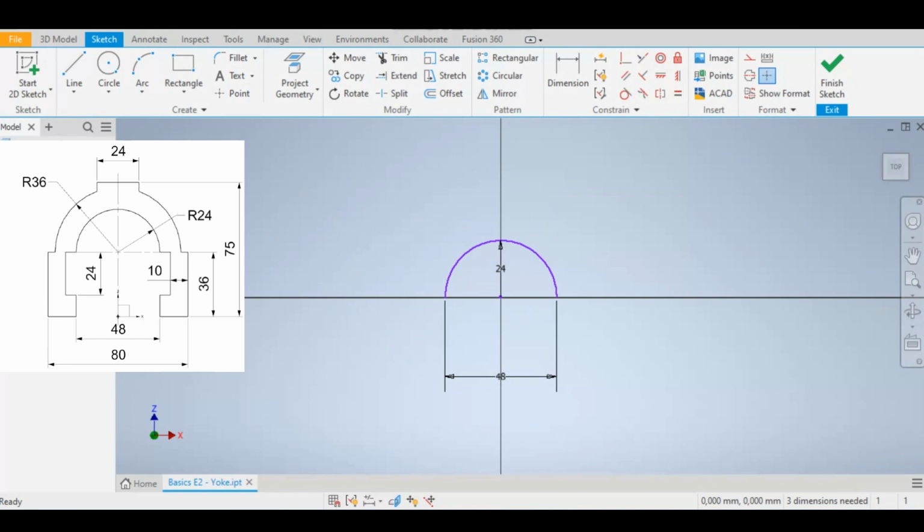And our second step, I'm going to draw the line at the top here. So to do some simple math, we know our X value will be a 12, and our Y value, we can enter simple math into our coordinate system and it will calculate the coordinate that you want to use.